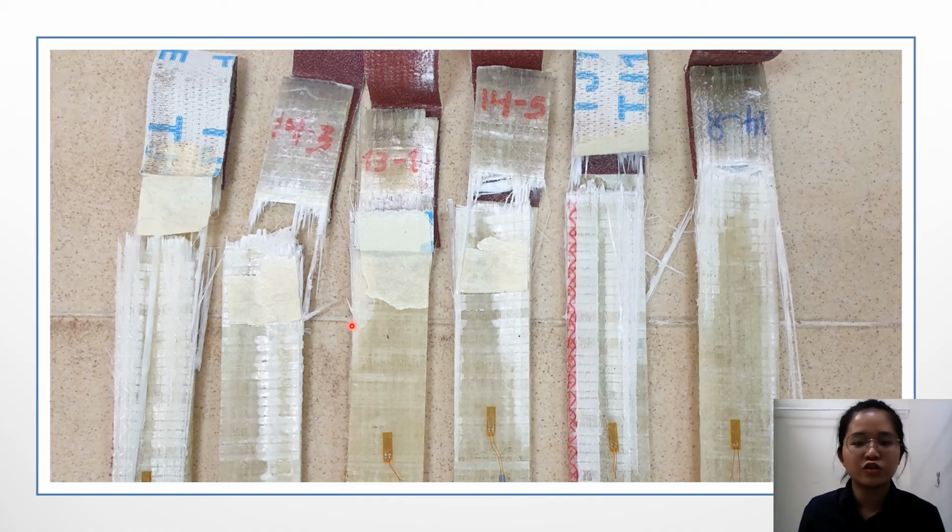Control samples show progressive failures. Progressive failure of FRP composite indicates that different parts of the failure surface of the composite reach the failure stage at different times. The progressive failure of control samples may be due to cracking of the matrix before the fiber.